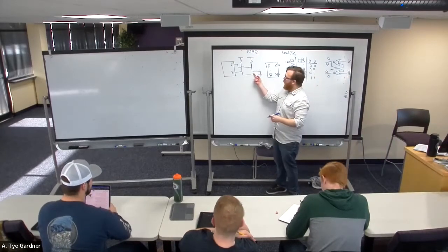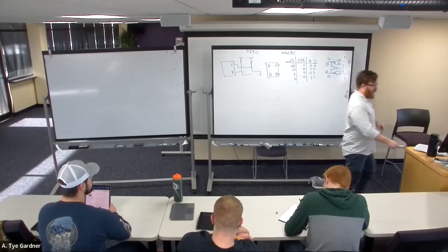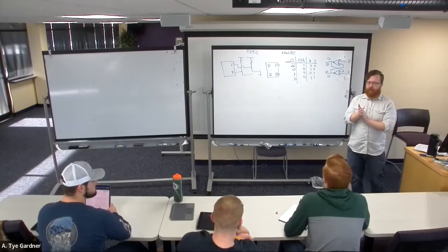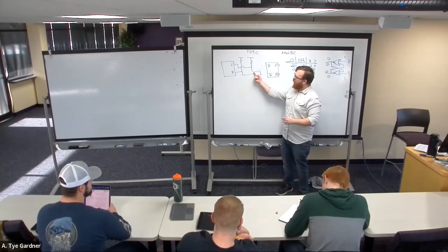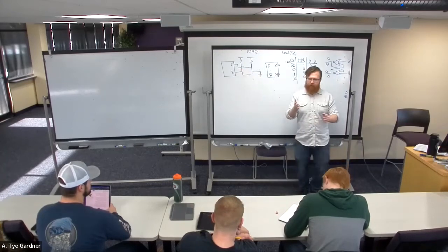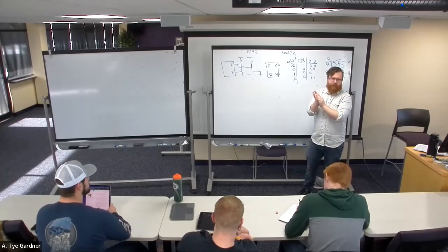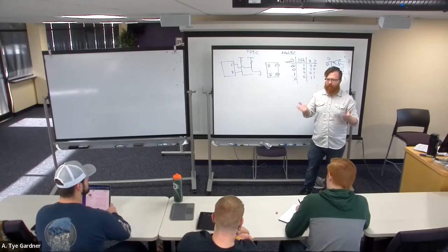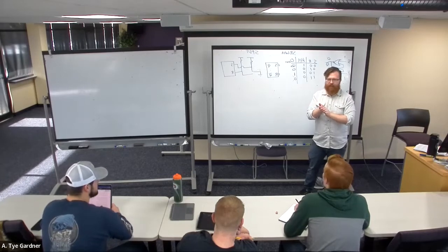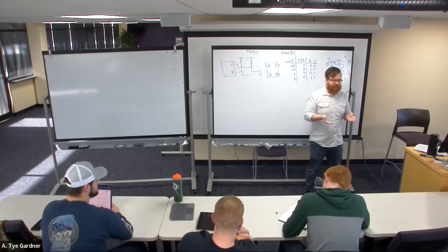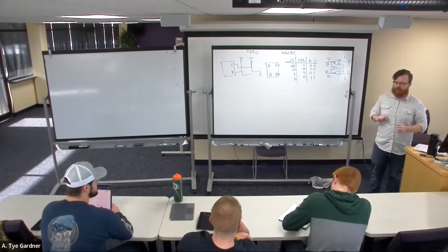So now when I throw my switch and it connects to set, so I'm sending a 1, instead of going 1, disconnect, what it's doing is now connecting to ground. So we probably would want active low here technically, but it's okay. And what's going to happen is it's going to go set. But guess what? If I set multiple times in a row, it's still just 1. The output will just go 1, 1, 1, 1, 1, 1 as it bounces. So the bounce doesn't matter. It no longer has a problem with the bounce, fixed by just that simple circuit.